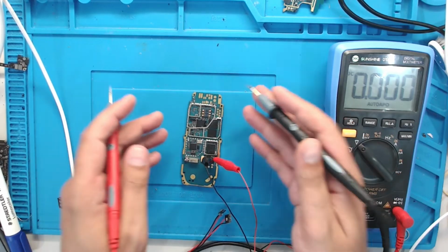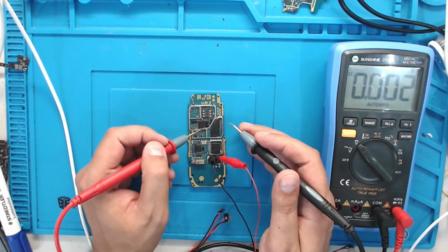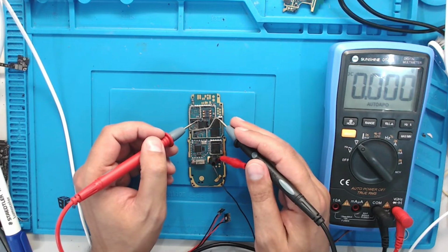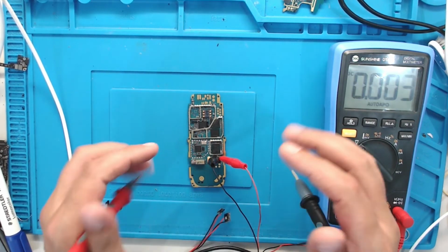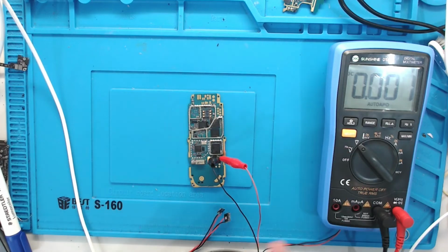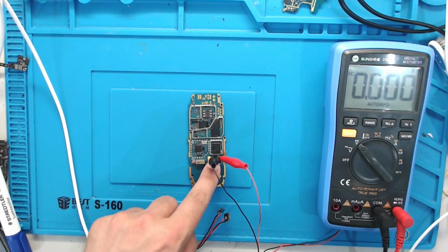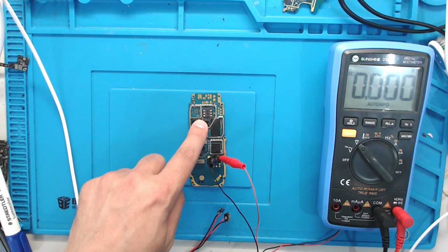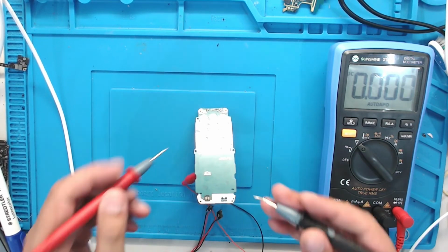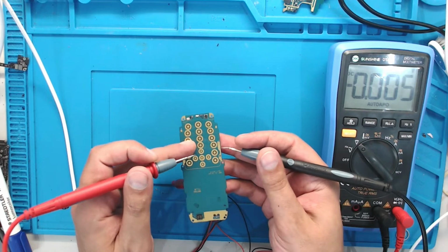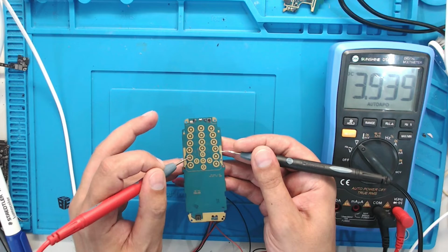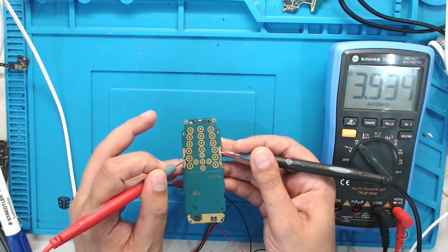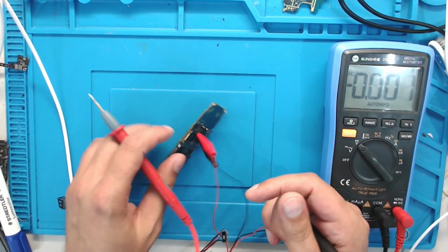Now we know this voltage comes to the power management unit. I check whether there is 4 volts again in here or not. You see, the voltage comes to here. Now we know we have the voltage in there. That means this voltage comes to the power management unit. And if you want to check the power key, again we check whether the power key has a voltage or not. We check 3.9 volts on the power key. That means all tests are okay.